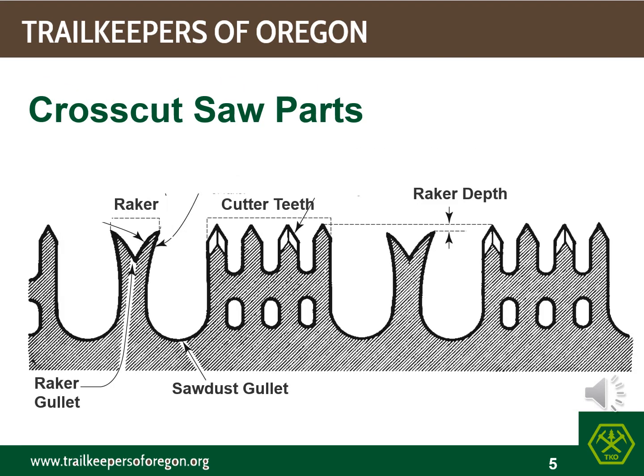Most crosscut saws are comprised of two types of teeth, cutter teeth and raker teeth. The gullet is between the two and is designed to hold the cut wood until the saw can drop that cut wood outside of the log. There's quite a bit of technical information on dimensions and angles for both the cutter and raker teeth. Competent saw filers can make your day, a saw that sings in operation. On the other hand, a badly worn saw, or one that becomes out of tune, will become a misery whip in operation.